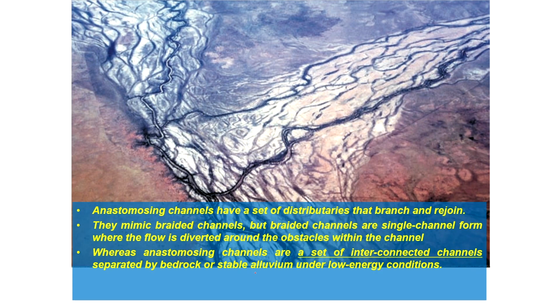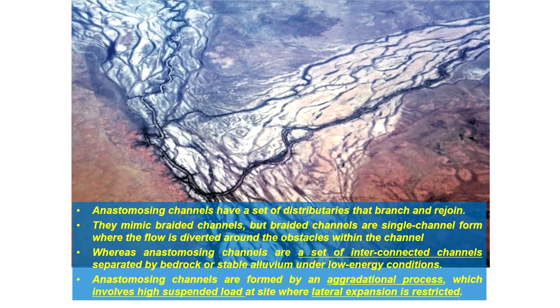separated by bedrock or stable alluvium, that is again bars, under low energy conditions. So there we are seeing high energy conditions, but here it will have low energy conditions. And anastomotic channels are formed by an aggradation process. That's a depositional process which involves high suspended load.